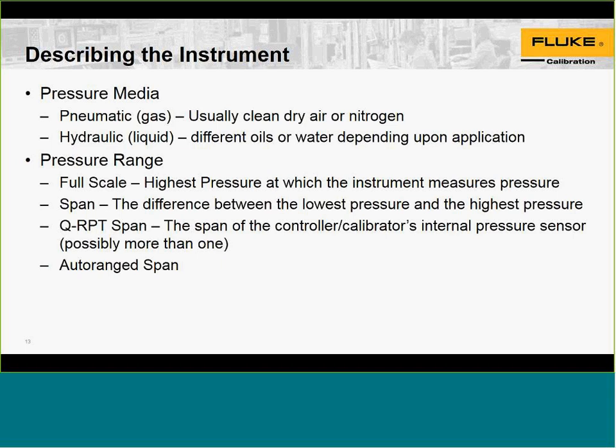In most cases, pneumatic is used for lower pressure applications, and hydraulic is used for higher pressures. Between the two, it usually depends on the application and the resources available to you. I calibrate some 10,000 psi sensors with oil. It's safer and less volatile than if you're using gas. But then there are also considerations of cleanliness and contamination. So it's always based on the application and with safety in mind.